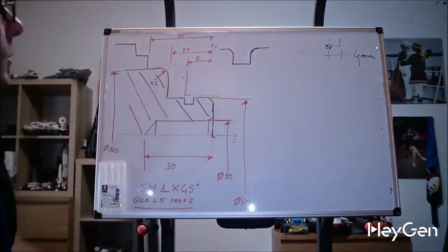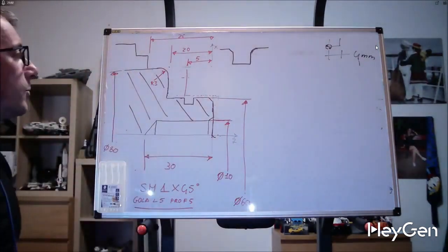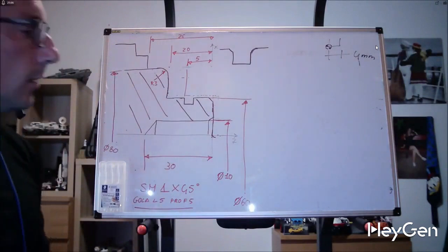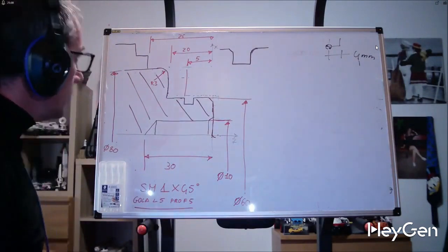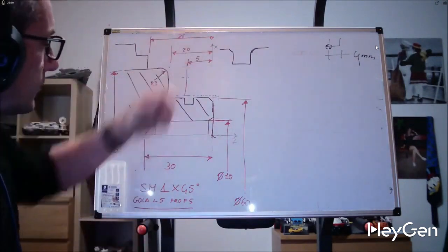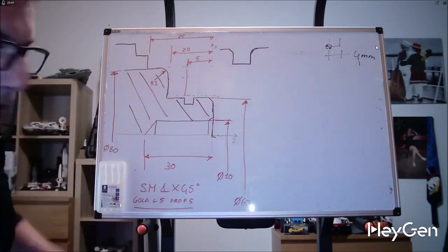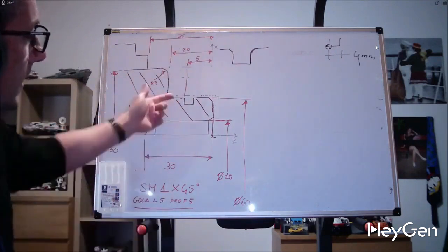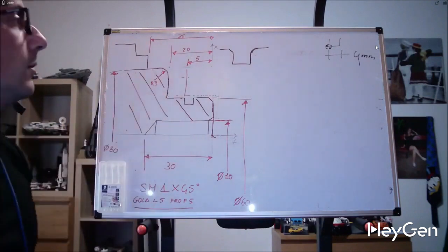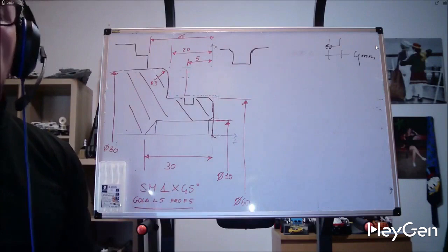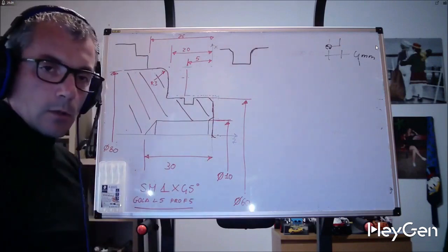Well, we can certainly make this groove point by point very simply. Let's not worry, as always, about many things like chips. The chamfer is 1, the radius is 1, the groove is 5 wide and 5 millimeters deep, which means it goes from a diameter of 60 down to a diameter of 50.